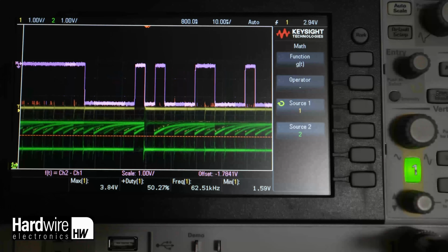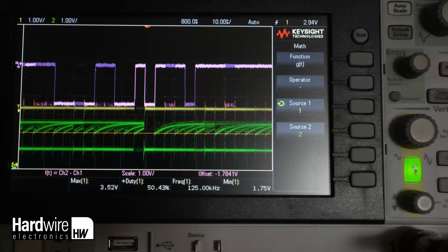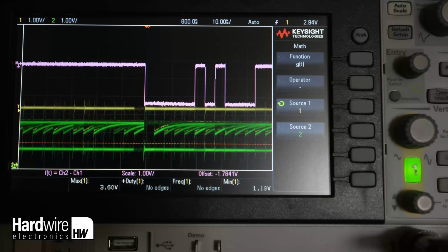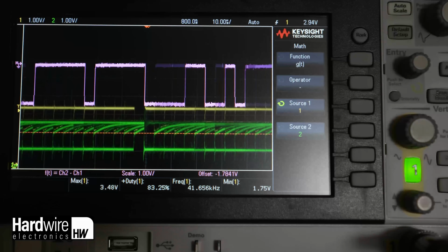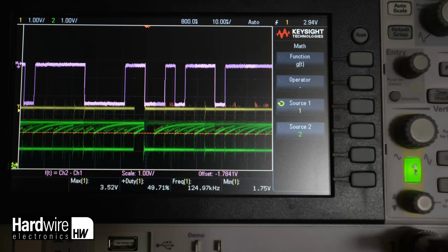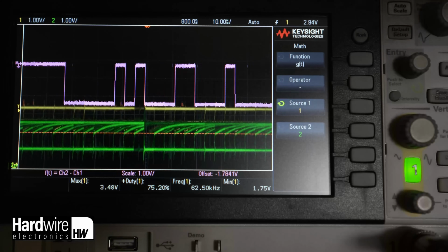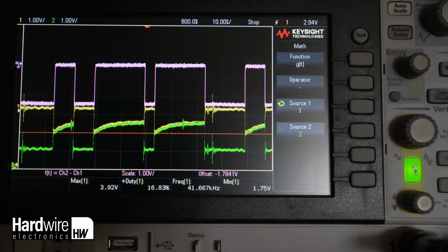Okay, so just to demonstrate this effect a little bit more clearly, I've actually set up a CAN bus in real life, and I've got an oscilloscope probe on both the CAN high and the CAN low wires. At the minute the scope's running, so you can't see too much, but if I just freeze frame this for a second, what you can see, I purposely made it so that there's a little bit of noise which has been induced onto the CAN high and the CAN low lines.